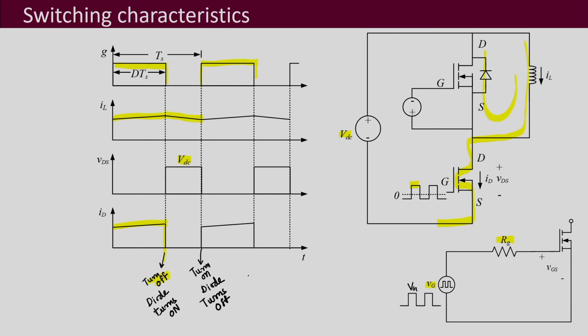That also means there will be an influence of the diode turn off characteristics while the MOSFET is turning on, because we have studied before that a diode, while turning off, has reverse recovery current and reverse recovery charge associated with it, and we should expect to see that effect while the MOSFET is turning on.